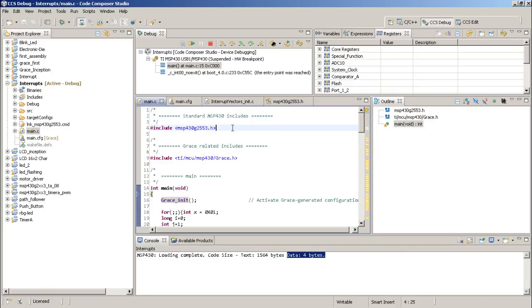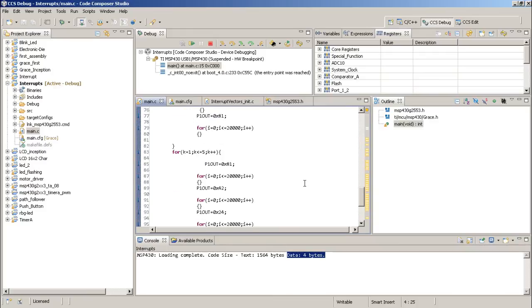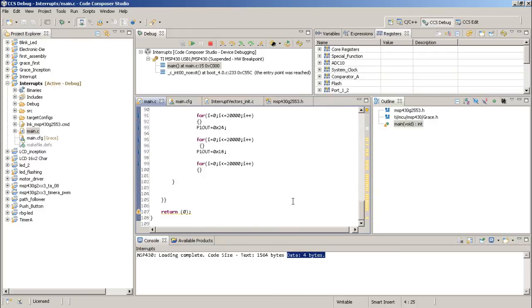There will be contact made, then the contact will be broken, so the port may get re-triggered. That is switch debouncing. It can be avoided by using flip-flops. I'll be talking about switch debouncing maybe in a separate blog entry.